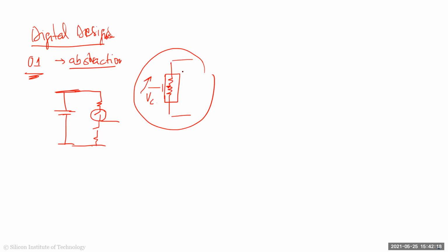The functioning is completely different in a MOS. In a MOS, it's capacitively controlled, so you don't have any DC current flowing through it. Now in finer technologies, you do because of quantum tunneling, but typically anything above 65, 45 nanometer, you don't see that.